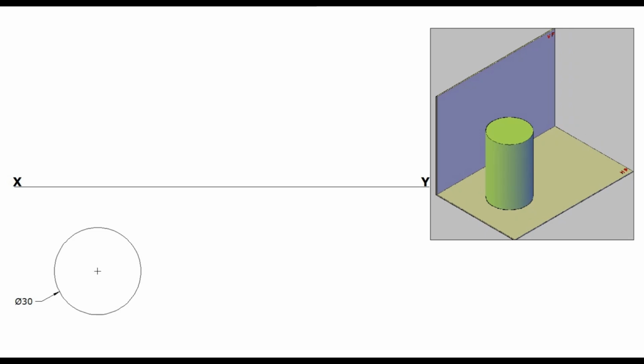Since the cylinder does not have any base corners or base edges, for our convenience of projections, divide the circle into an equal number of segments. Divide the circle into 8 equal parts and name these points as 1, 2, 3, 4, 5, 6, 7 and 8. Cylinder has two bases, one at the top and one at the bottom. Divisional points of the top base can be named as A, B, C, D, E, F, G and H.